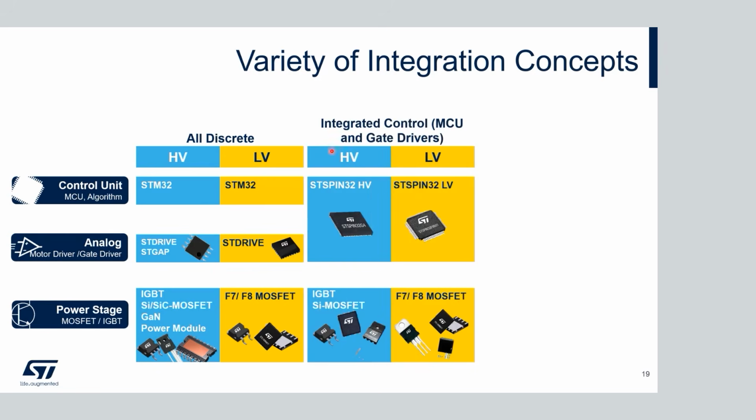If we make integrated control, so we integrate the microcontroller and the gate driver into one package, then we call that an ST-SPIN32 approach. And here we have products for high voltage application and low voltage application available. Then you have all of these gate drivers, for instance. If you think about this kind of gate driver, this is just a half bridge, or this is a single gate driver on the picture here.